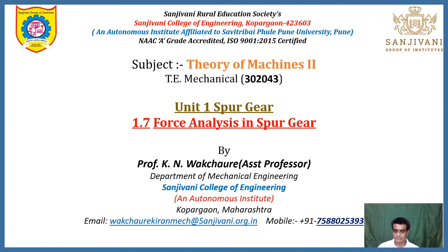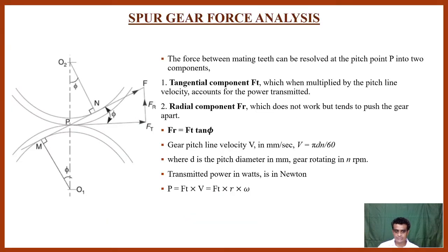That's why here we have to consider only two types of forces. One is the radial force and one is the tangential force. One important thing that you should remember while studying any type of gear: in all types of gears, only the tangential force is required to transmit the power. Radial force tries to separate two gears radially and axial force tries to separate two gears axially. The only important force is the tangential force, which is responsible to transmit the motion. Okay, now just consider this geometry.